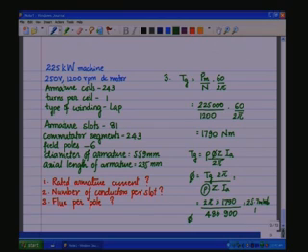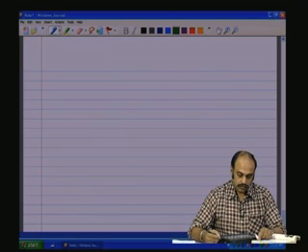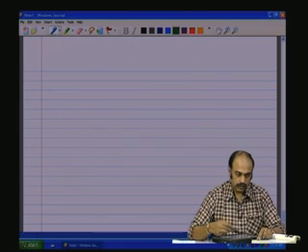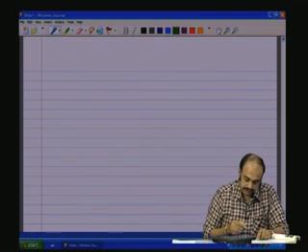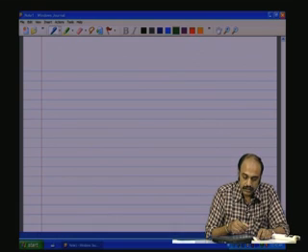So, this is flux per pole. This is the flux, and the flux per pole would be divided by 3 pole pairs for P, that is this one, which is approximately 8 milliwebers. So, this is how one goes about calculating the various parameters of the DC motor. Must have given you an idea about the usage of the equations.